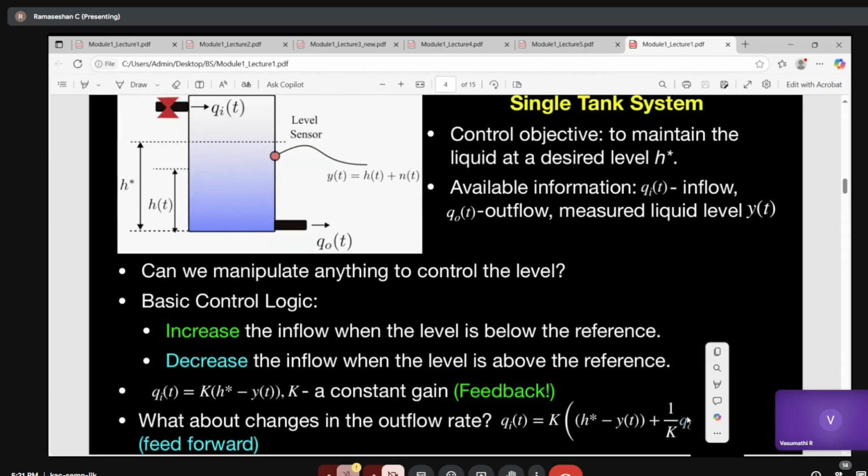But you know what reference input you want to give at 5 seconds, right? You know what the system wants to be after 5 seconds. So regarding the input signal, you have the knowledge of the future input values also. So you can utilize that to give an extra corrective measure. That is called the feed forward control.